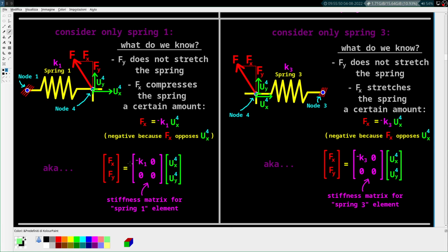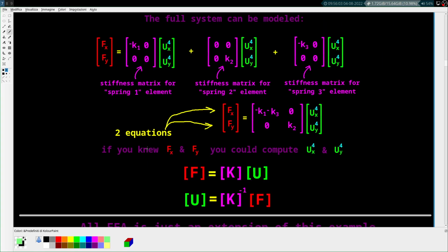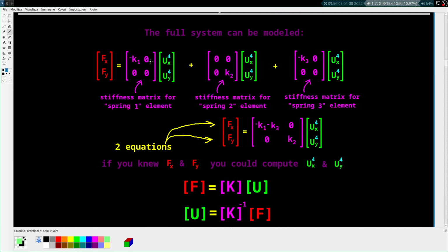And you can plug this into the equation. Now, in this case, row 2 times column 1 has nothing because there's no Fy in the equation, but Fx does have a value there. Long story short, you can take those terms and add them together. What does this mean? Well, this means that the force has to be distributed across all of the elements per their stiffness coefficients k. And so you can add these together, you can undistribute the degrees of freedom and pull out this matrix equation here. So 2 equations, 2 unknowns.